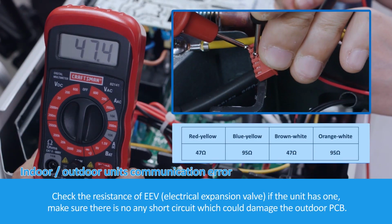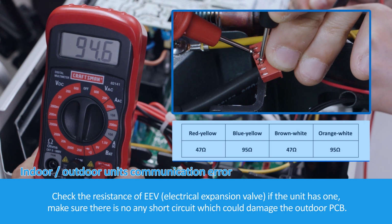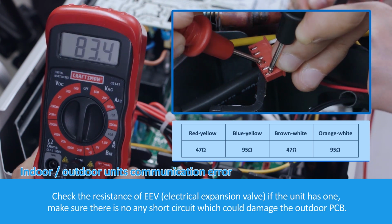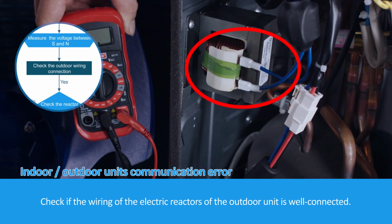Check the resistance of EEV, an electrical expansion valve. If the unit has one, make sure there is no any short circuits which could be damaged at the outdoor PCB. Check if the wiring of the electric reactors of the outdoor unit is well connected.